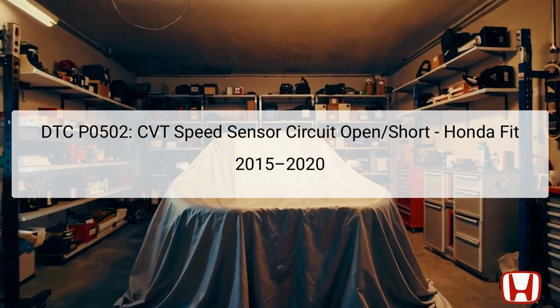The Diagnostic Trouble Code, DTC P0502, for the Honda Fit from the model years 2015 to 2020 indicates a malfunction within the continuous variable transmission, or CVT, speed sensor circuit. It specifically highlights an open or short circuit within the system, meaning there is an electrical issue rather than a mechanical problem in the transmission.